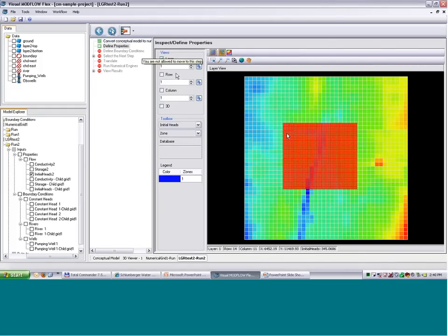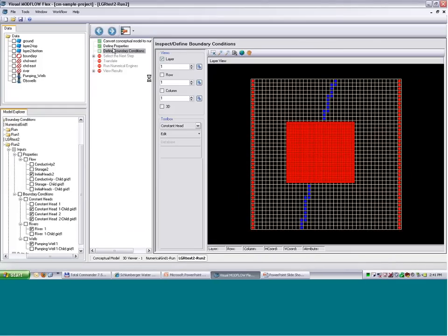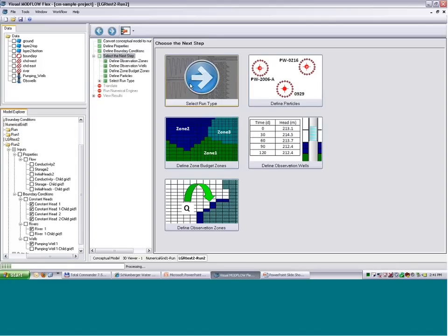So this corresponding numerical model can also be translated and run. When you do the translation, it'll create those files in a separate Modflow directory where you can also post-process if you need to, but you can also run this numerical model and get corresponding heads and results. And this allows you to compare different numerical model representations from one scenario to another. Essentially it allows you to streamline the model development, so you don't have to worry about getting the right grid dimensions the first time. You can try several scenarios, whether they be 50-foot cells or 100-foot cells or whatnot, generate the numerical model and see what the results look like in a few mouse clicks, as you can see here.